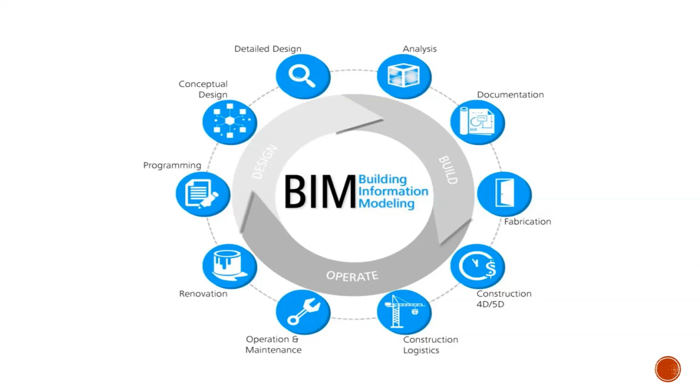And after that, one thing is there that will be called clash detection. So I said different designs will be there. Before going for the preparation of construction documentation, all the clashes between these different disciplines should be resolved. For example, if I have a structural beam and column section in a framed structure, there will be column, beam, and slab sections. And the MEP engineers will be providing HVAC duct piping or plumbing piping, etc. So whenever there is an interference between structural members and MEP members, I have to resolve that in the design stage itself.